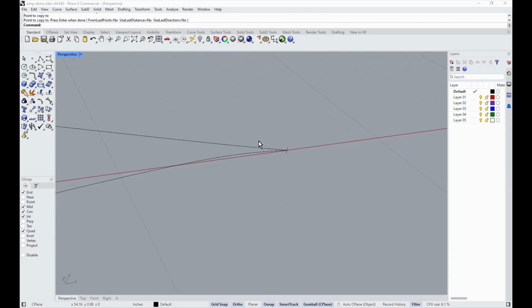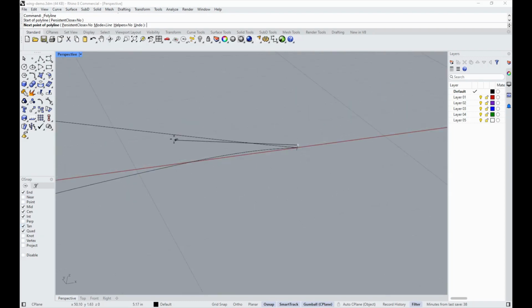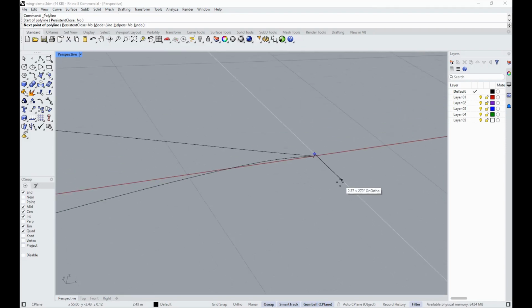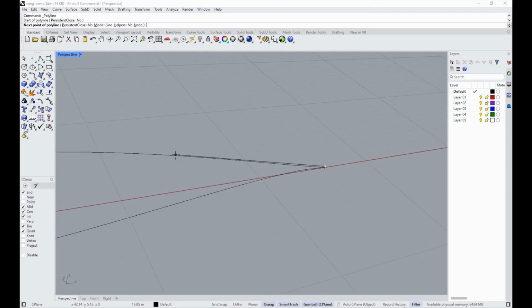And we're going to probably think of, let's see here. Normally what you would do is they usually will split the difference with this right on the trailing edge. So we can go grab that line, turn off ortho, turn off grid. Now we need tangent on here, so we got to turn on tangent. If it hunts for it, there we go. There's tangent.